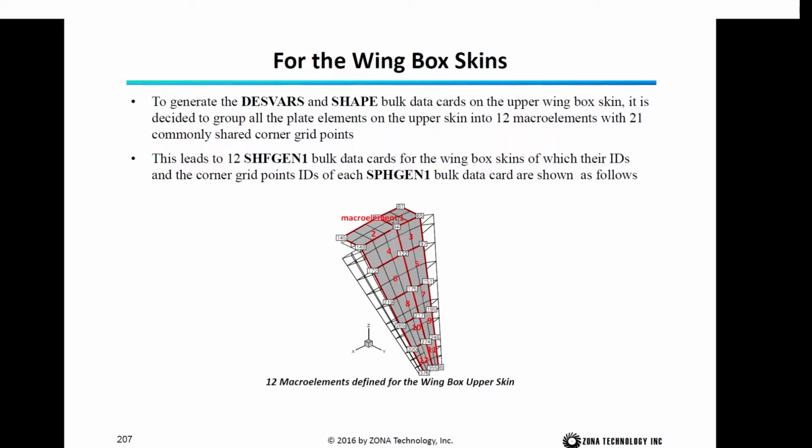For example, we have grid point 94, and the thickness at grid point 94 is 1, and it is shared by 4 macro elements. So the Lagrange shape functions become 0 at the boundary of those 4 macro elements, and at the center, the grid, it is 1.